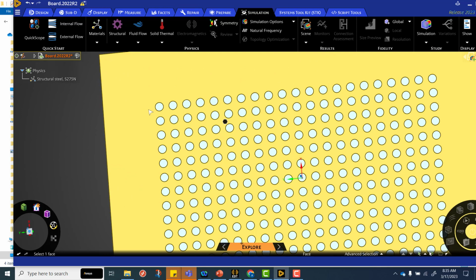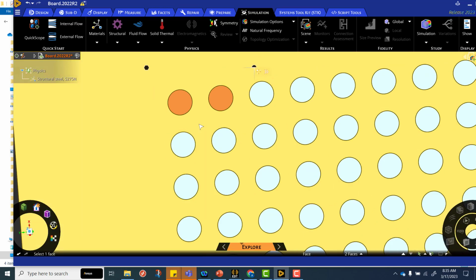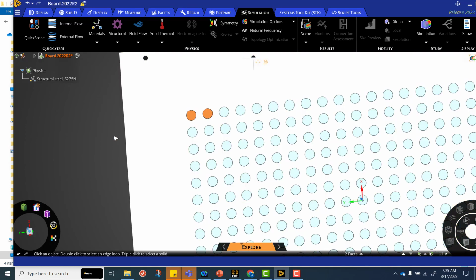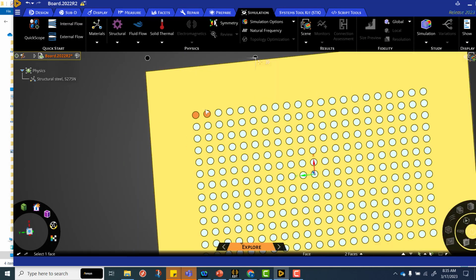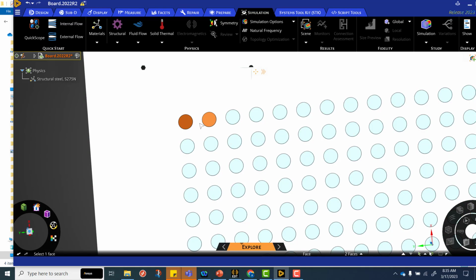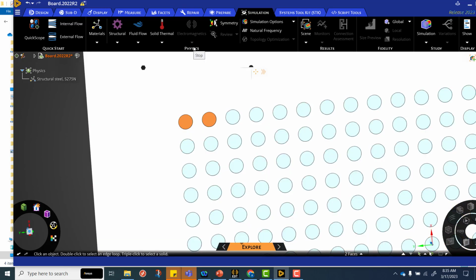One of the critical tasks here is to determine how far apart any two anchor magnets might be separated and still allow the magnet to fall through. That's a case that we set up in class and we talked about, and we're going to do that right now as our final goal for task 4 of this project, to be able to determine what the minimum, or I should say the maximum separation might be to still be able to hold a float magnet and have it reach equilibrium without falling through.